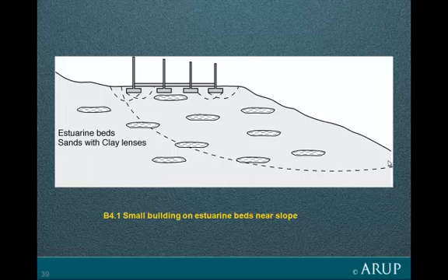On the other hand, when it comes to thinking about the bearing capacity, is it possible that some of the footings could be dominated by a clay lens? Have I eliminated that possibility? If I haven't, then I have to design the footings for the clay. And the characteristic strength of these beds would be different for the footing design from what they would be for the overall stability design. On the other hand, again, I might say, well, I'll eliminate that possibility because I'll probe every footing situation. And if I find some clay, I'll dig it out. So I'm now sure that it's sand. And again, I can take a much more optimistic view of the ground conditions. So it depends how you do the investigation, and it depends on the size of the zone of ground. Will it average out a lot of these things, or will it not be able to?